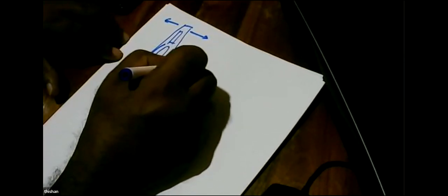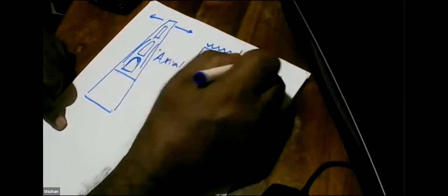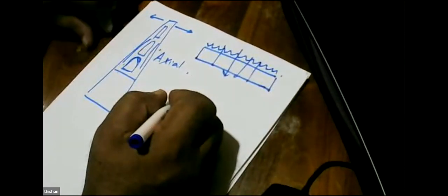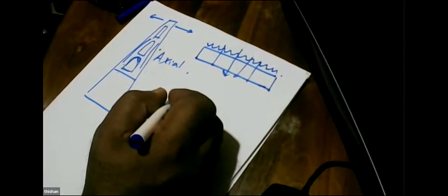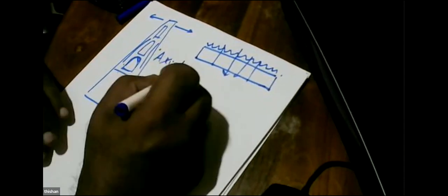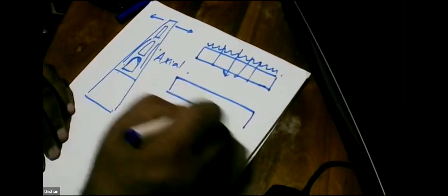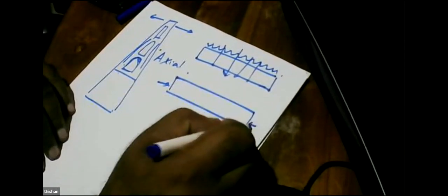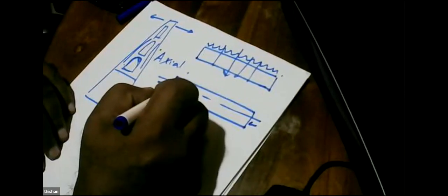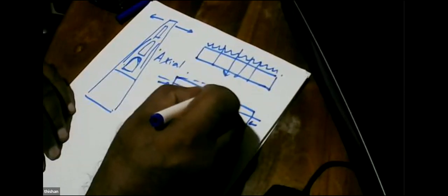And we really don't know whether it will bend this way or this way, we don't know. So what is preferred? Axial stress. So what is preferred is axial. On the other hand, we have a beam, and we know it's going to be loaded only in one direction, and that is downwards. So if that is going to be behaving downwards, what we can do, if you know the behavior, is we apply the pre-stress at an eccentricity and make it bend upwards.